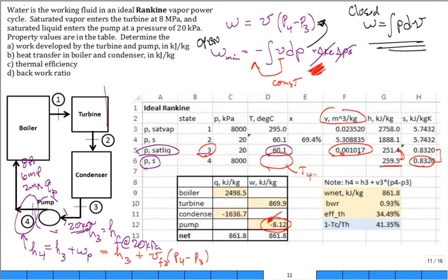But I think the pressures that the compressed liquid table starts at are so high that if you're not in that table, you basically just have to remember it's just a little bit more than T3. So add a half a degree if you really needed it, or 1 degree. Or go get the software, which will do this calculation much more accurately. But it's a difficult task to get T4 out of our appendices.